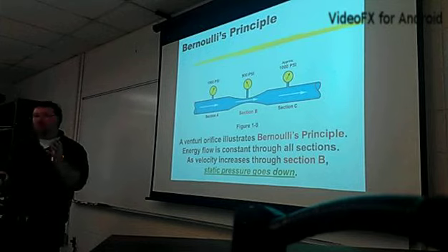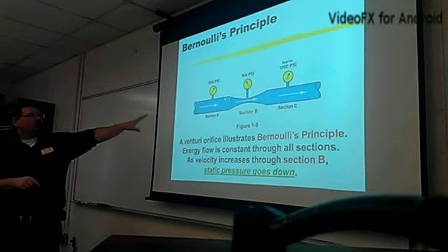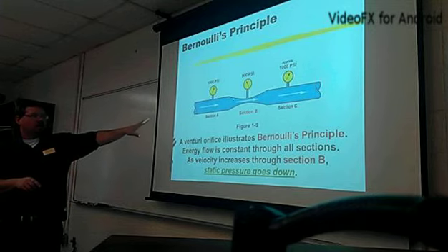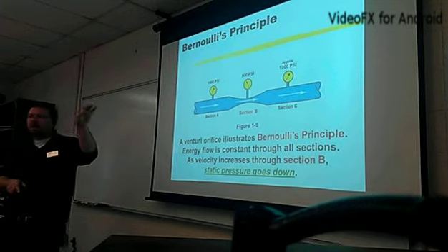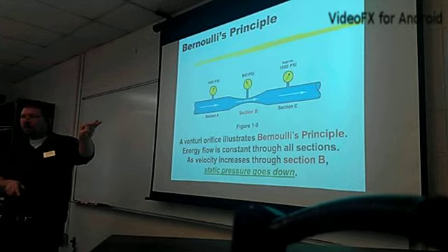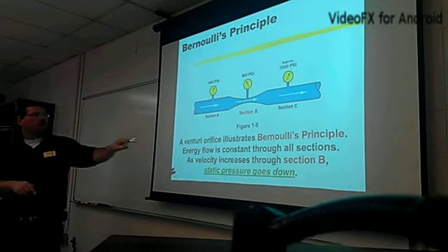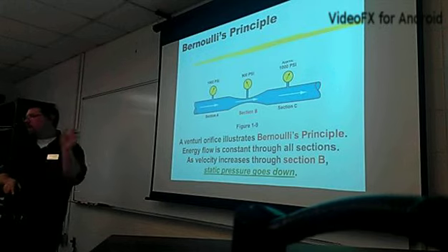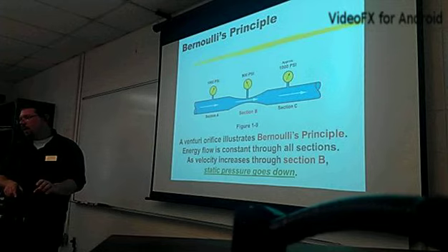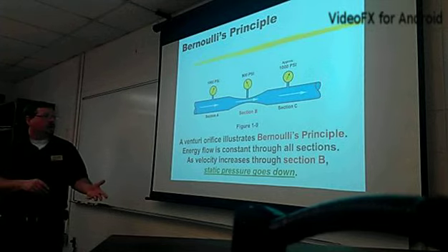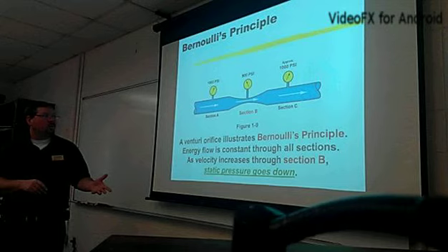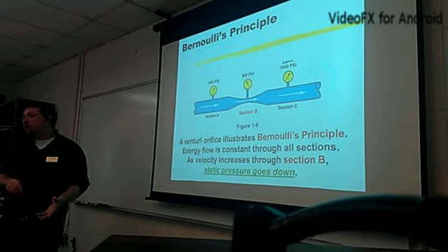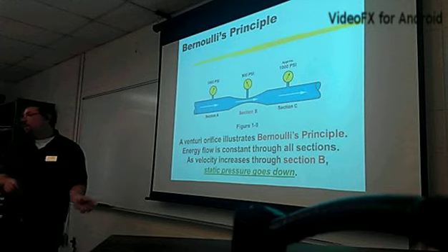This really applies in general. It has to look just like this. It has to be some kind of slope. It has to be narrowed, pinched. Okay. Now, at a certain point, the mass of the fluid gets to the point where it can't easily pass through that opening, and it depends on the thickness of the fluid or viscosity. And then it will actually begin to pull a vacuum and cavitate, which means that there'll be a vacuum pull behind it, and there'll be vacuum bubbles in there, and it'll make a big racket.